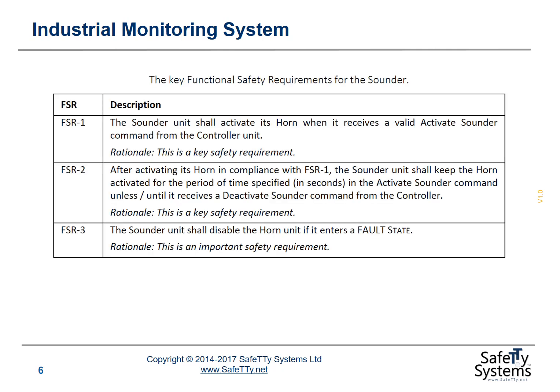So we've identified the following functional safety requirements for the sounder. Functional safety requirement 1. The sounder shall activate its horn when it receives a valid activate sounder command from the controller unit. This is clearly a key safety requirement.